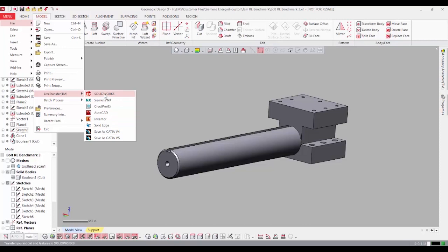It'll open up, you'll have SolidWorks in this case open, and it'll rebuild this tree in the native CAD system. It works pretty good on SolidWorks and Siemens. It's a bit more of a challenge with Creo. It works pretty good with Inventor, AutoCAD and Solid Edge. And for CATIA, you just get a native file, you don't get the history tree. But if for some reason you did want to edit this file and get the history tree, the live transfer is your other option.